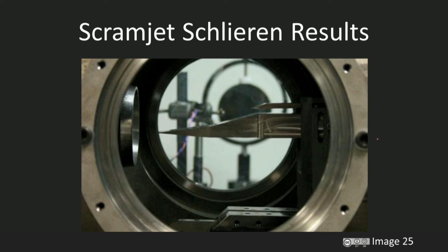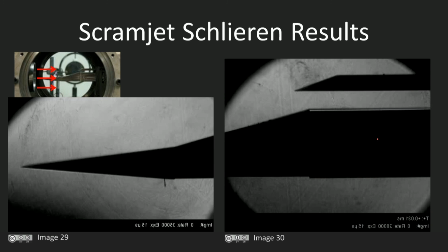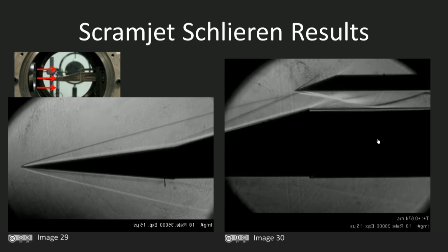Considering our scramjet intake in the test section, in these images, flow is travelling from left to right. Two separate Schlieren images have been taken in order to cover the full field of the view. We can now see compressible flow features with considerable detail.